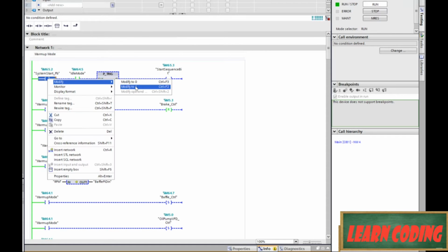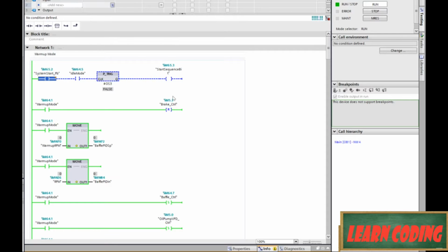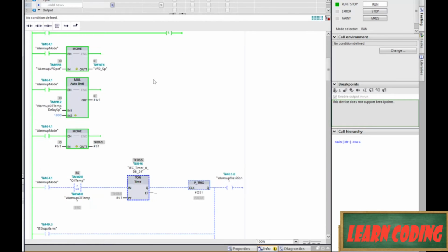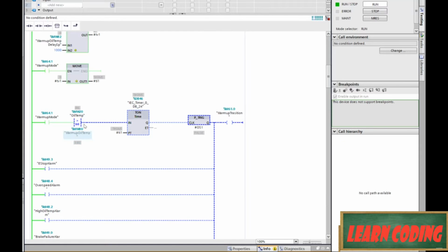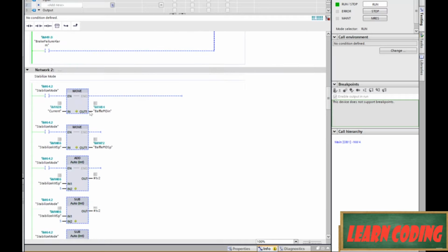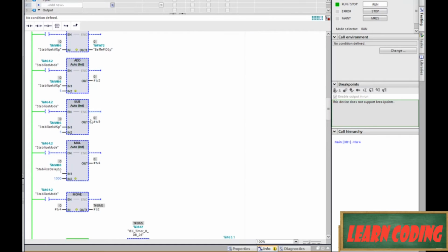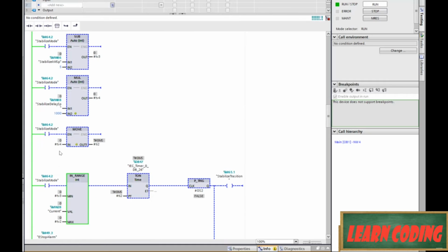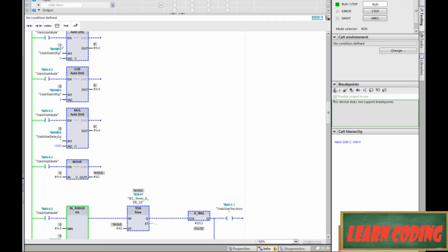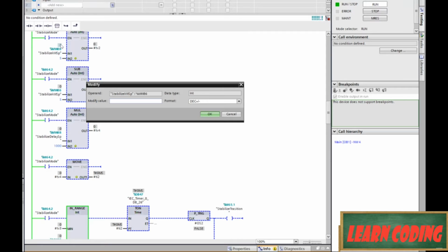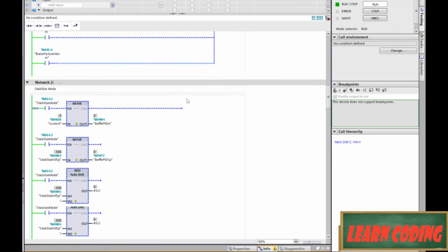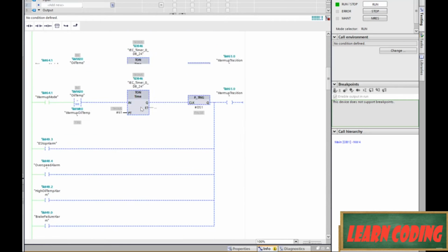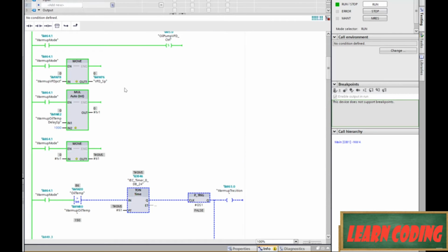Okay, so back to our start button, modify to 1, modify to 0. We are in warm-up mode, and we should be here until we get that oil temp. And let's go ahead and get our stabilize mode ready. So our stabilize mode, we need to set that set point value. So our stabilize set point that we're adding and subtracting on, yeah, let's go ahead and set that to something like 300.